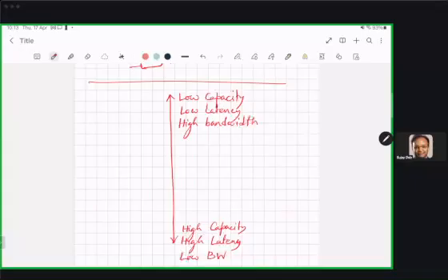So basically our registers require a lot more transistors to implement. That's why I can't have too big memory, so low capacity. It has very fast performance, basically low latency, and it can be read and written very quickly. That's why high bandwidth. And this is DRAM. SRAM sits somewhere in between. Okay, and because of that,